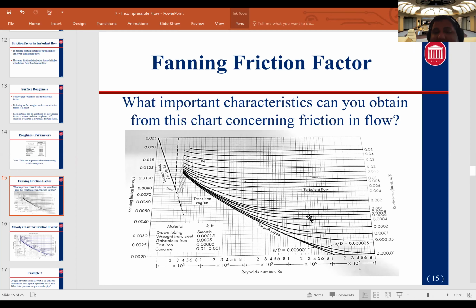And that isn't done by accident. What that is here to illustrate is that once you get to a sufficiently high Reynolds number for most systems, the friction factor becomes a constant value. Essentially, the friction factor becomes fixed, and your frictional dissipation becomes entirely dependent on the flow velocity.